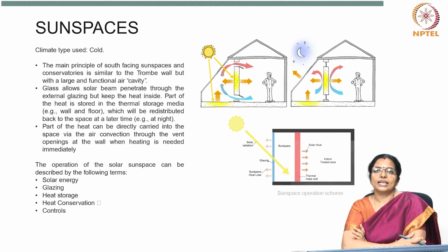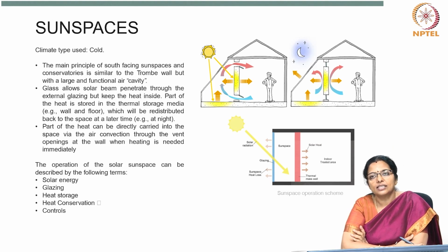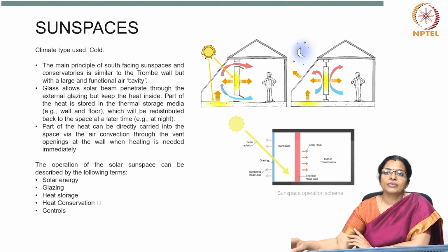The effect of the glazing is that the glazing is responsible for the solar gains and the heat losses. Transmittance happens, which is the radiation that is neither reflected nor absorbed, that is called transmitted. Translucency and transparency of the material is another important factor.